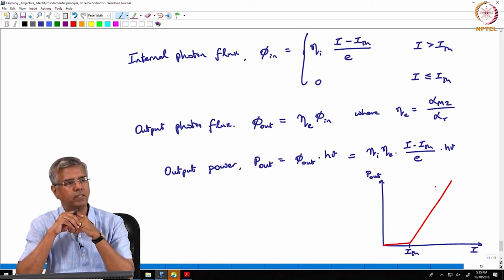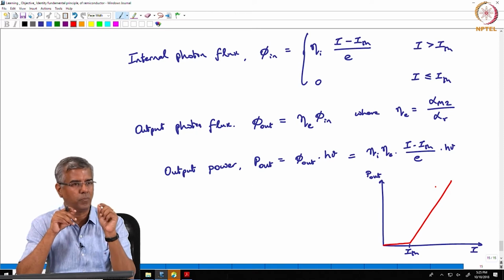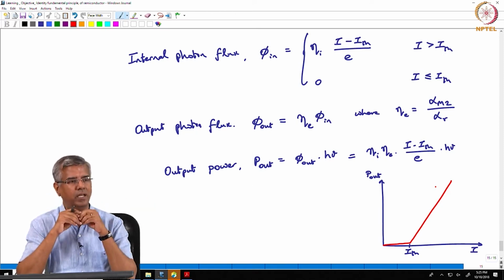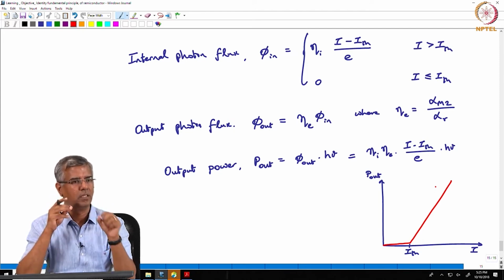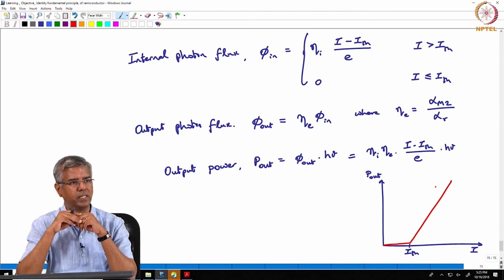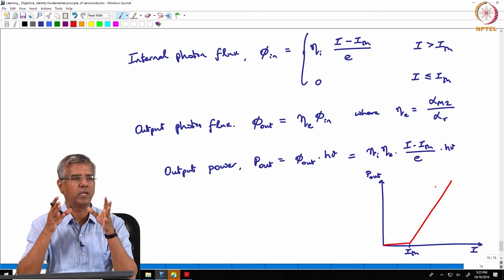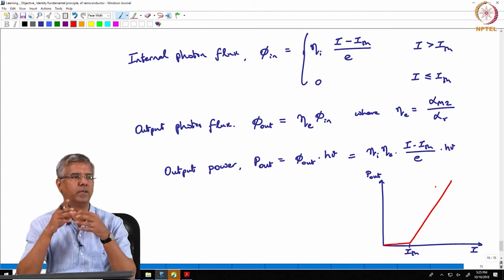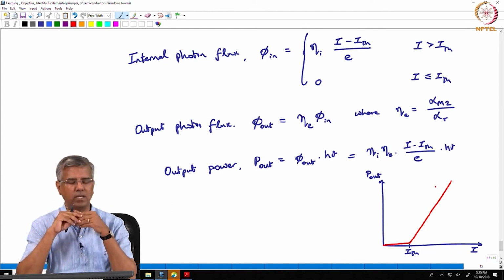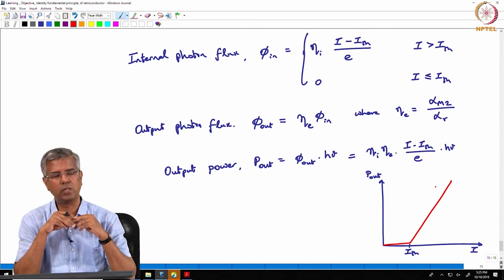The shorter the wavelength, the smaller the spot size that you can get, because the diffraction limit scales as a function of wavelength. So, the shorter the wavelength, the smaller the feature sizes you can get. So, if you want to do lithography with very small features, you use ultraviolet light sources, and lasers can be used for that.